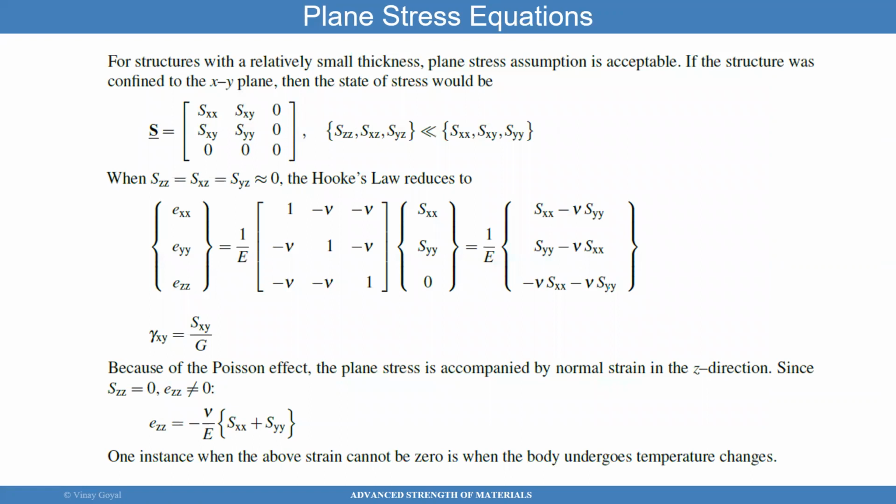So in my book, I explain what that implies. What it implies is that these stress states that have to do with the z direction are close to 0. I'm not ignoring anything. I'm just saying that stress states are close to 0 for those components. So these are much lower in magnitude than this one. Much lower is what I use in my book. Okay.